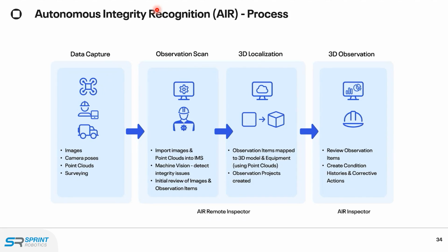Sometimes, if you look at advanced NDT, for example, phased array, we don't process phased array data within IMS. You do that outside, but you bring the outcome, the results of that analysis, into IMS, and that will trigger the integrity management or the degradation management of your system. Good.